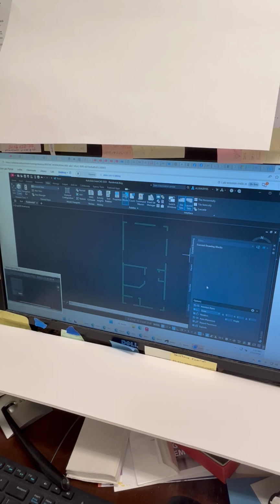Notice the scale factors can vary between X and Y axes. For instance, if I had a square block, I could say I want the X axis to be 2 times the original, and then the block comes in already stretched. But I don't want to do that here.